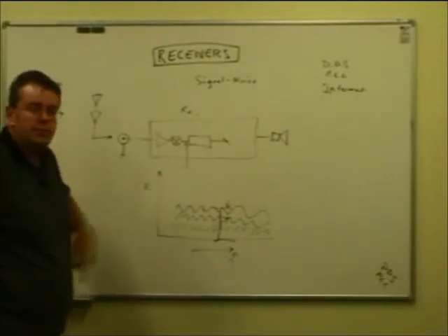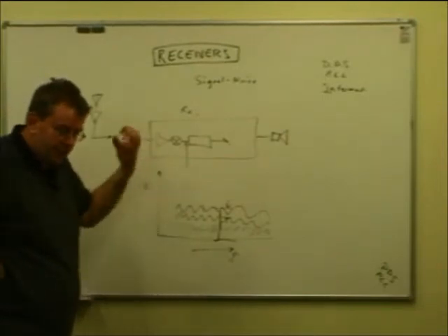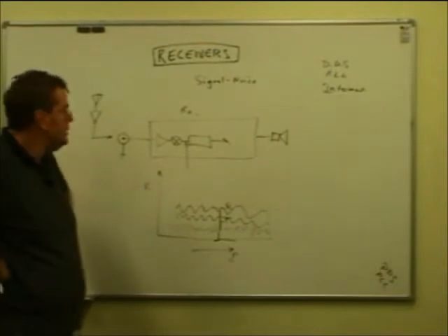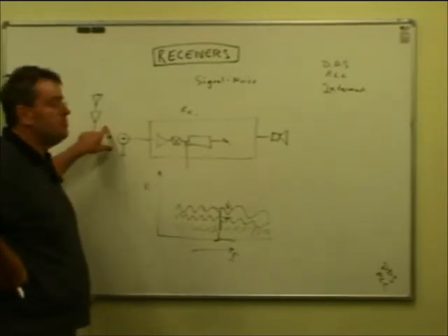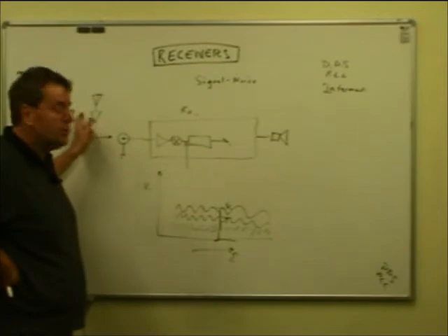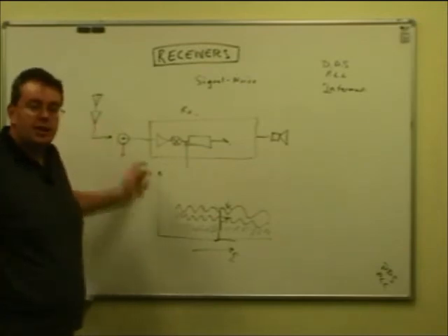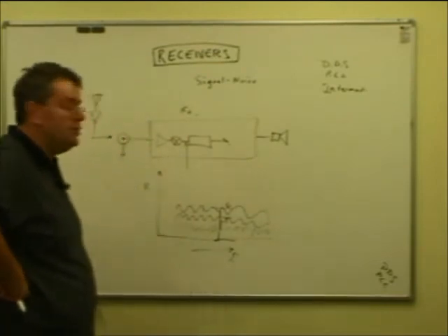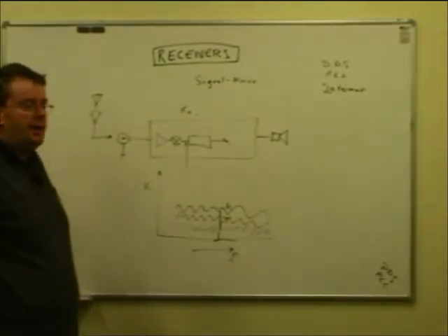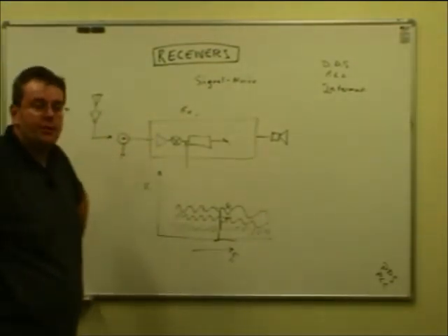It's the random motion of the electrons in the coaxial cable from heat that will add noise to the signal as the signal weakens going down the coaxial cable. So the signal to noise ratio is at its best actually at the aerial terminals, and it deteriorates as it goes down the coaxial cable. That's not normally much of a problem at HF bands, but at VHF, UHF and microwave, that's quite critical where you might be dealing with very weak signals.